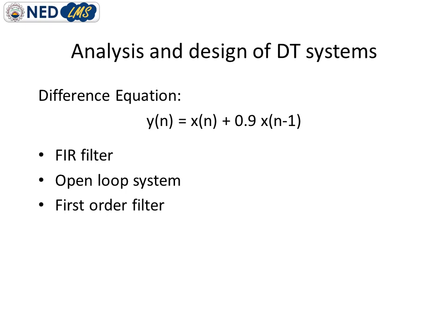This system is basically a discrete time system, or an FIR system, or an open loop system, or having no feedback, and the order of this system is first order. So all this information which I just told you is on the basis of looking at its difference equation.